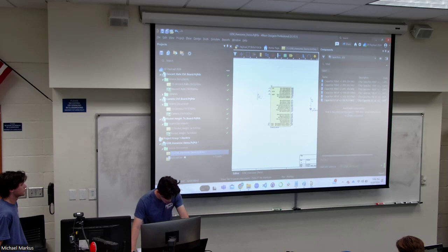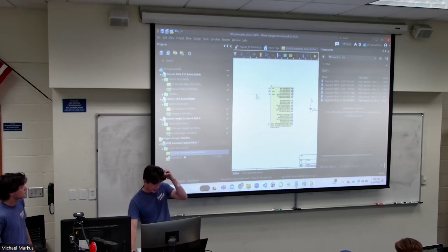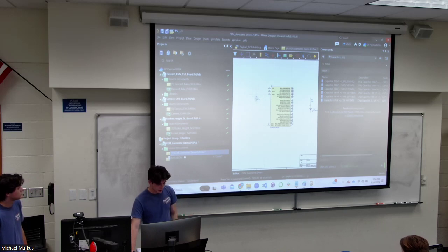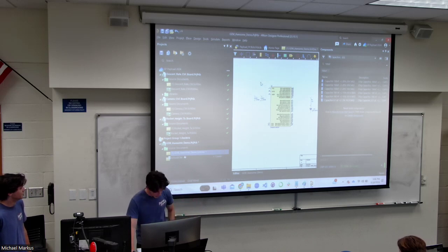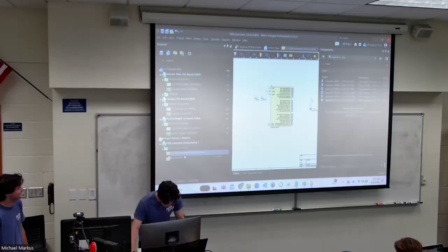And so we have a VCC, an AVCC, and an AREF. We're going to ignore the AREF. That has to do with the analog to digital converter. It's not necessarily the best practice to leave it floating, but in this case it's fine since you can select the reference to be AVCC. It likely wouldn't cause any issues, though that's not necessarily the best practice. Okay, we have that. So we have two of those.